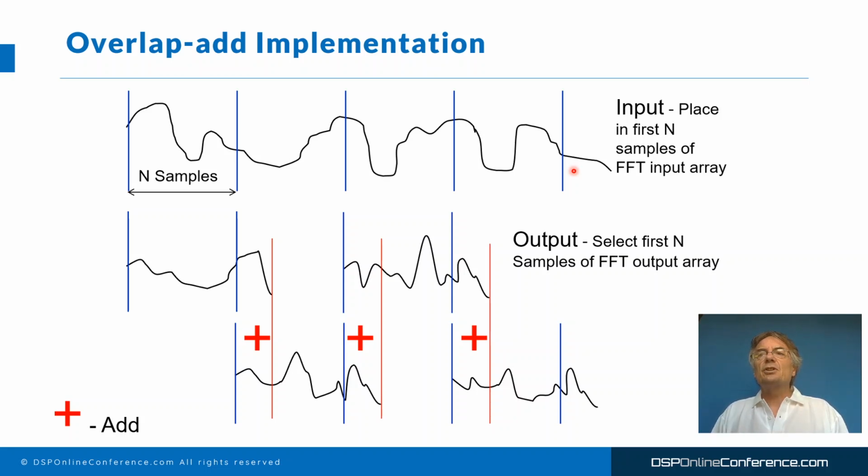If we take two blocks of data, our n samples of the time domain and our big M coefficients of our filter, if we convolve independent arrays of data, then the output array length would be the sum of the two input array lengths minus 1.